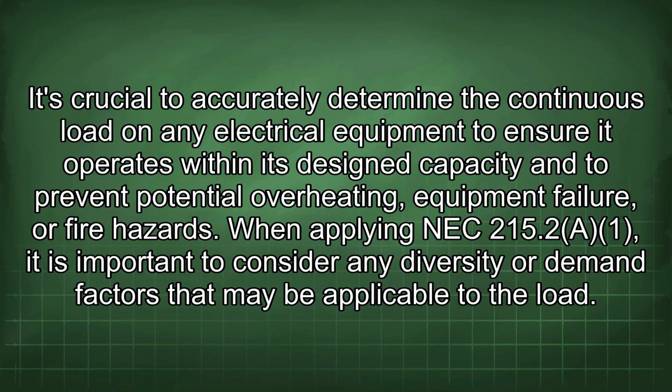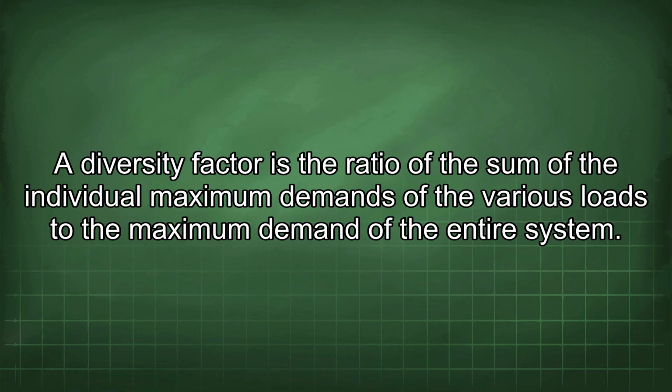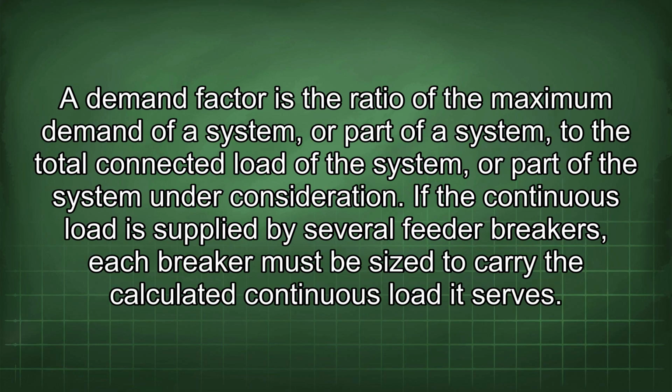When applying NEC 215.2(A), it is important to consider any diversity or demand factors that may be applicable to the load. A diversity factor is the ratio of the sum of the individual maximum demands of the various loads to the maximum demand of the entire system. A demand factor is the ratio of the maximum demand of a system or part of a system to the total connected load of the system or part of the system under consideration.